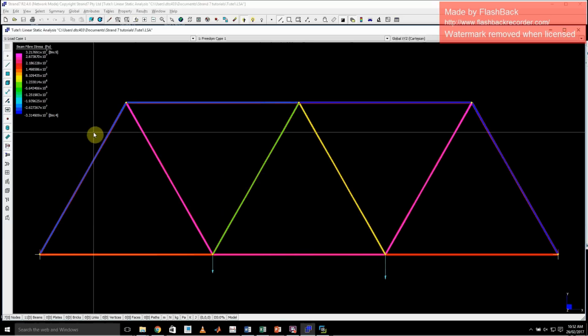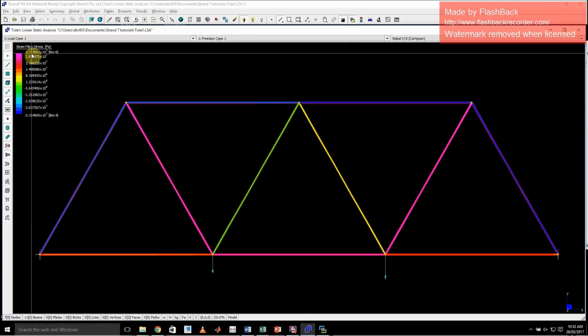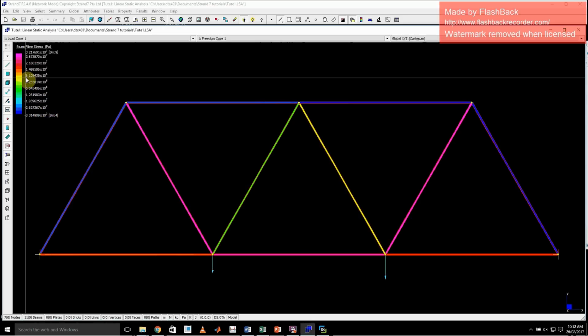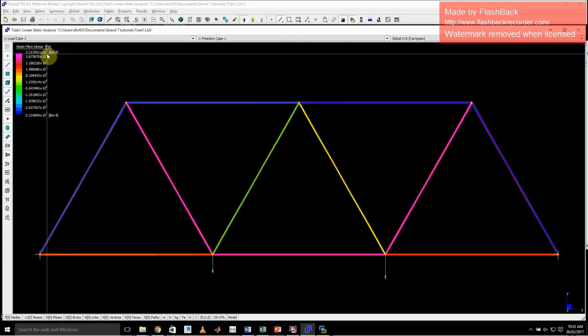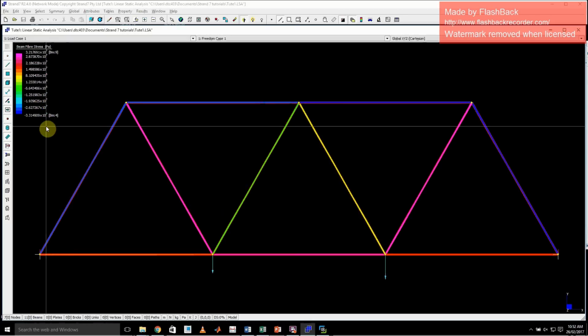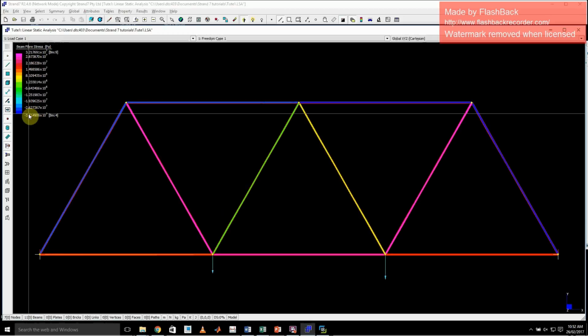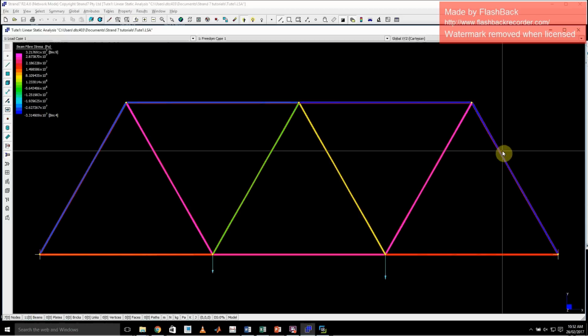So again, we've got a minimum down here of 33 megapascals, maximum of 32 megapascals. This is always going to represent itself in scientific notation, so make sure you're coming in checking the exponent here. Yes, that is 8, but it's 8 by 10 to the 6. This is 3 by 10 to the 7. So get used to checking this. Again, pascals, not great units. Megapascals, much more useful.